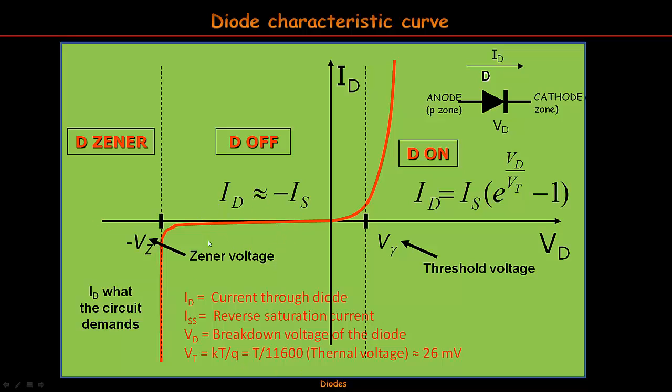Diode is not conducting. We are in this area and there is a minimum inverse current of saturation, mainly negligible, nanoamperes. There is an extreme zone, here it is, where the current is what the circuit demands. If it is regulated by fabrication, it could be named the Zener zone, and the voltage of the junction will be constant, no matter the current across the Zener voltage. On the contrary, the diode can be damaged. This would be the breakdown voltage.